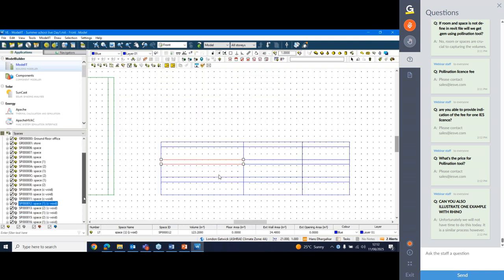So if you want to draw voids, it's up to you. The room height is now 2.2, and the void height is 0.8. And those rooms are void categories. You can see they're gray instead of yellow. So thermal zones, conditioned zones are yellow, unconditioned zones like voids are gray. You can convert them manually if you wish to yourself.